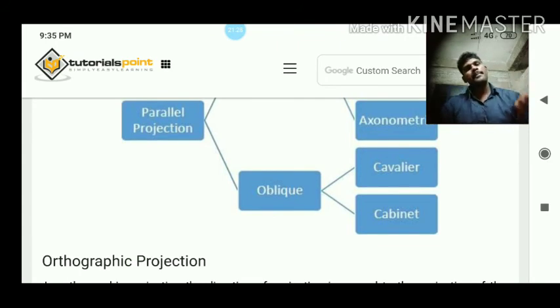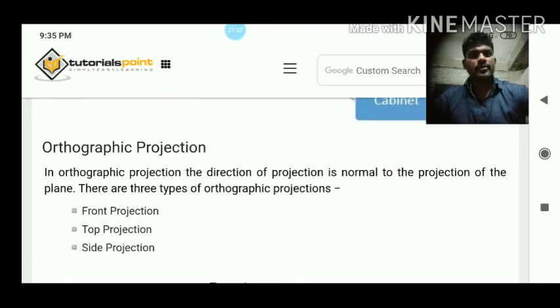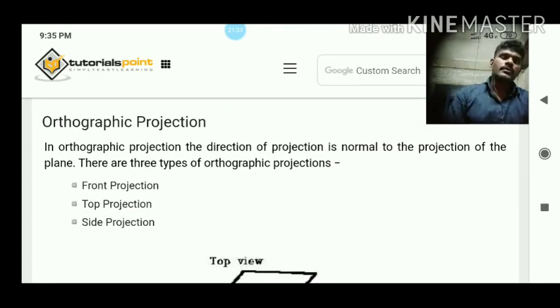These are the parallel projections. So now we will see orthographic projection. What is orthographic projection? In orthographic projection, the direction of projection is normal to the plane of projection. There are three types of orthographic projections: front projection, top projection, and side projection. What is the top view, front view, and side view?